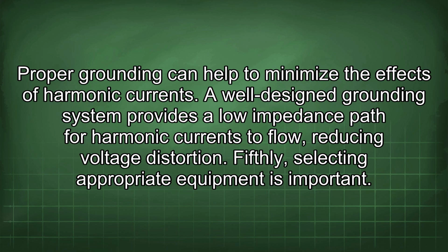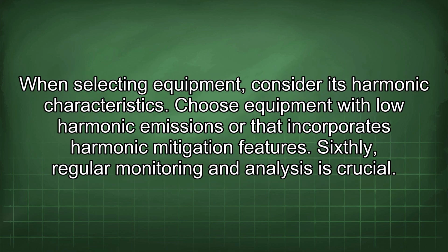Fifthly, selecting appropriate equipment is important. When selecting equipment, consider its harmonic characteristics. Choose equipment with low harmonic emissions or that incorporates harmonic mitigation features.